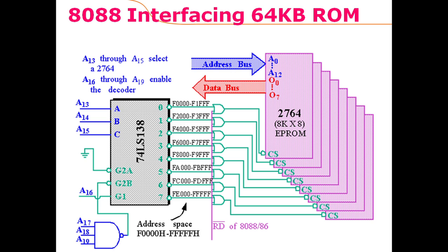So to do that, every chip has a chip select pin that is low active, and as there are 8 kilo locations inside each chip, 13 bits are sufficient to address each location inside each chip. So these 13 address lines are connected with every chip in this array, and similarly each of these chips has 8-bit capacity in every location.